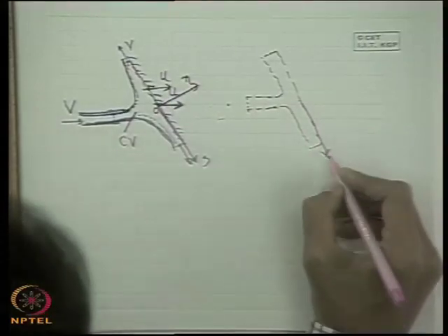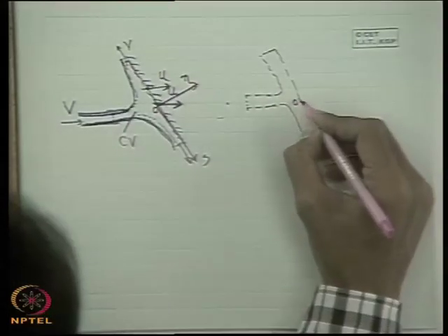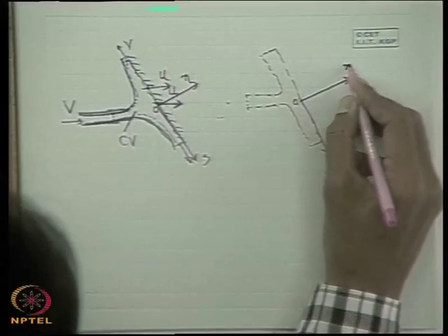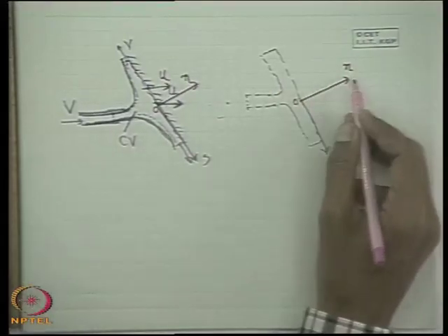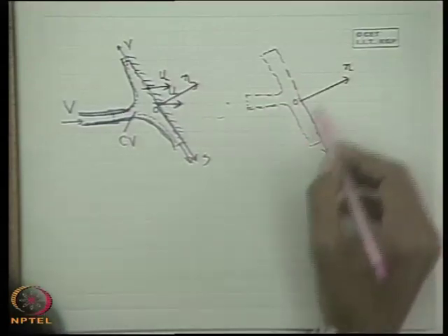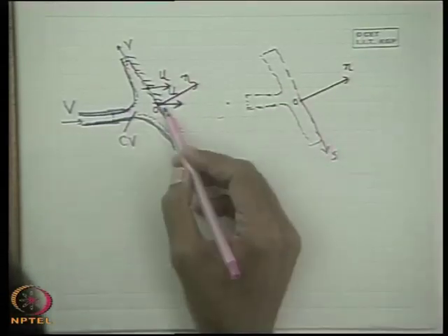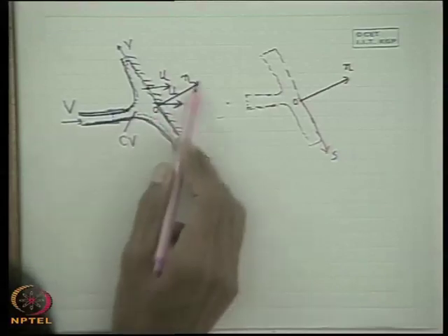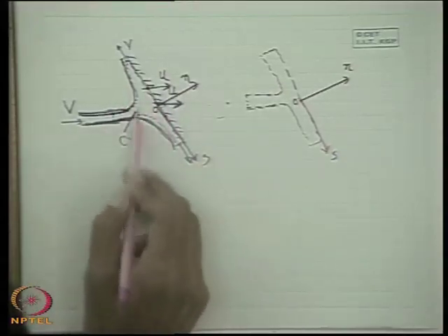Therefore, to make the problem steady, we attach the coordinate axis to the control volume, that is a moving coordinate axis. Sometimes in the language of mechanics we say the coordinate axis is moving. You can define it that way also: with a moving frame of reference the flow situation may remain steady.